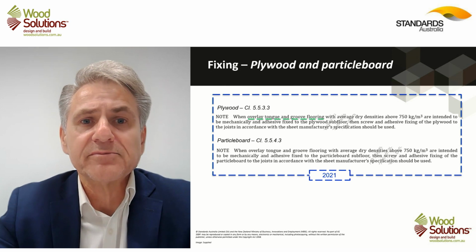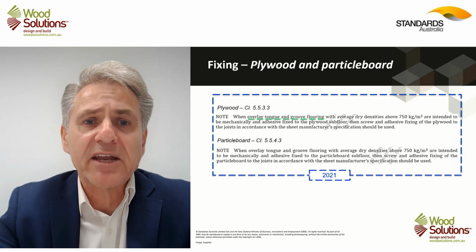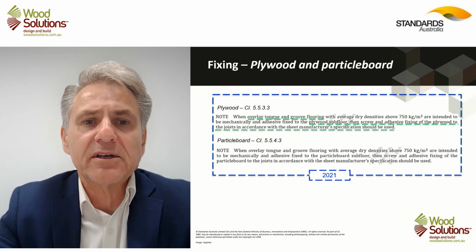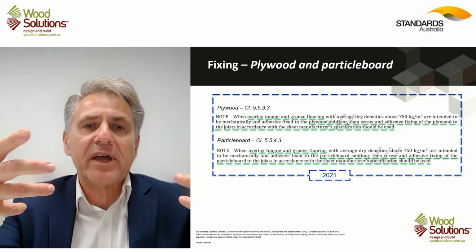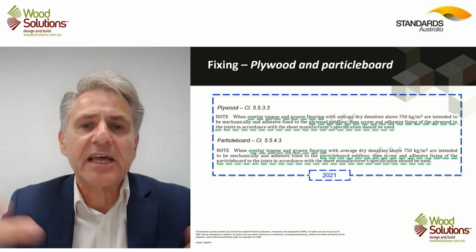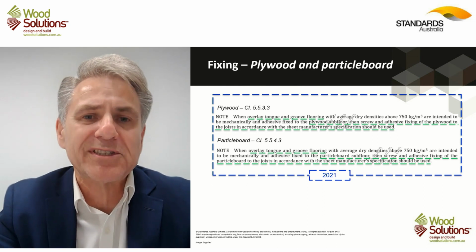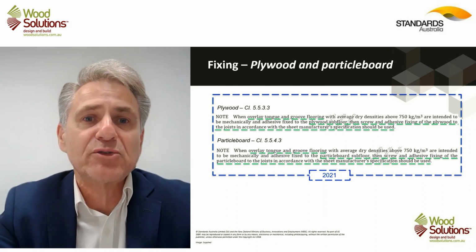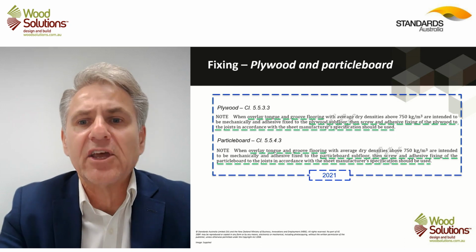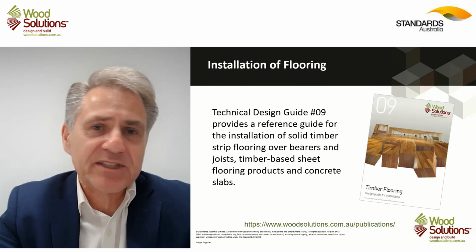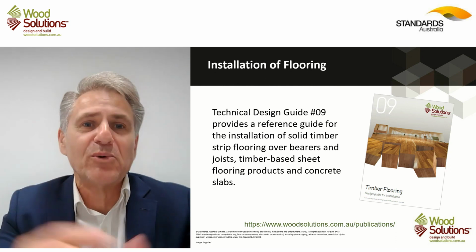based on experience. So the installing of plywood and particle board, nothing too different there, it just talks about the use of adhesives and mechanical fixing, or when we're doing particle board as well, same sort of thing, where we can also apply a flooring or an overlay to that substrate, plywood or particle board, but just making the point, we want to make sure that our substrates are well fixed to our floor joists or battens prior to installing any overlay.